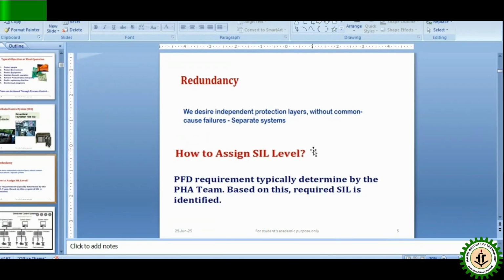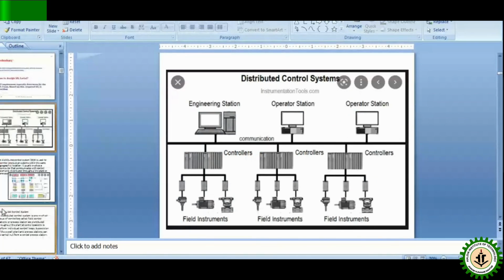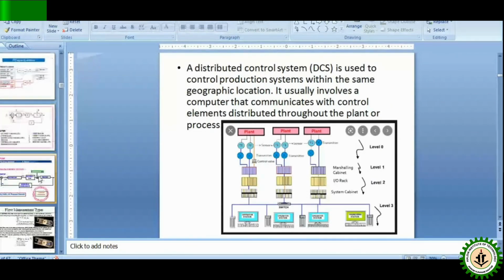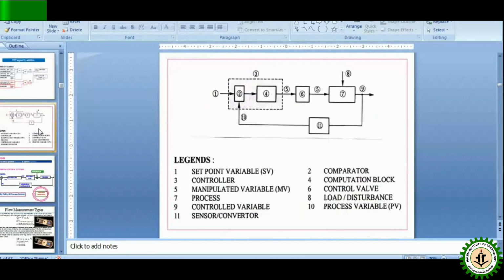Like you are measuring the level in a vessel and you are putting two level indicators, but one level indicator is sufficient. The purpose is if one level indicator fails, and it is a toxic chemical, it should not overflow. Another level indicator will take care of the level. So this is how things go. This is the architecture. I will not go into detail on that. This is the very basic thing you have to remember.